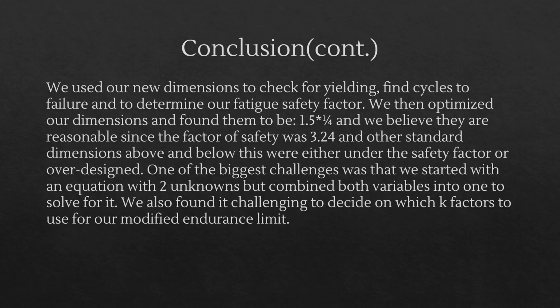We then optimized our dimensions and found them to be 1.5 inches for our outer diameter and 1/4 inch for our thickness, and we believe they are reasonable since the factor of safety was 3.24. And the other standard dimensions above and below this were either under the safety factor or over-designed.